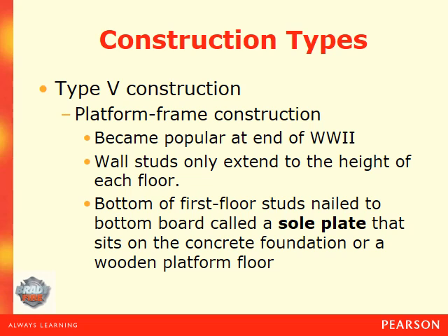Next, you have the Type 5 construction that is known as platform frame construction, and it became popular at the end of World War II. So wall studs only extended to the height of each floor. So basically you had a firewall or a fire gap, something to prevent the fire from spreading. The bottom of the first floor studs were nailed to the bottom board called a sole plate that's set on the concrete foundation or wooden platform floor.